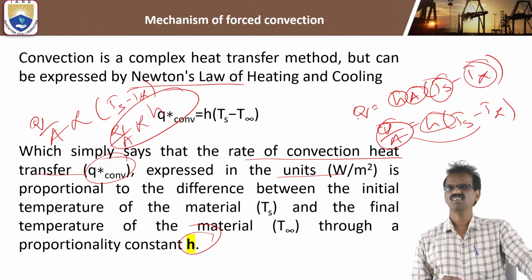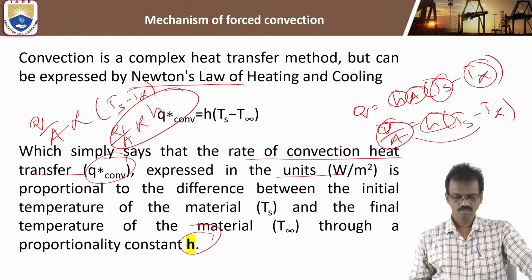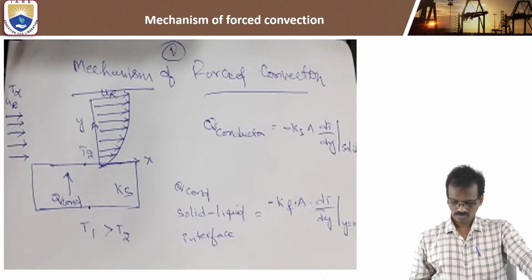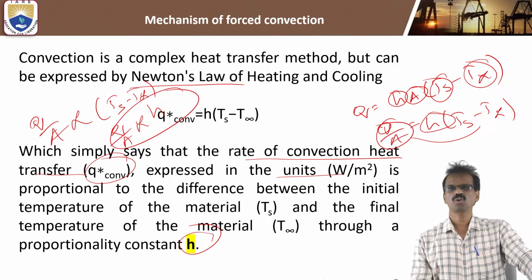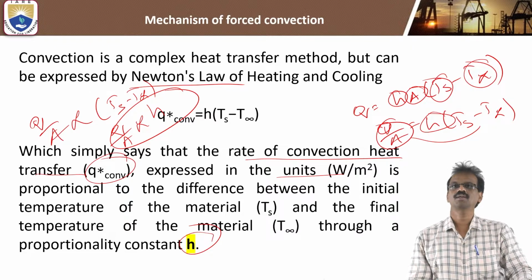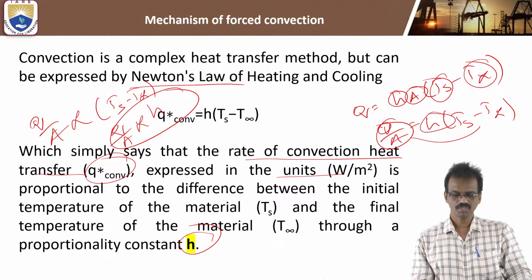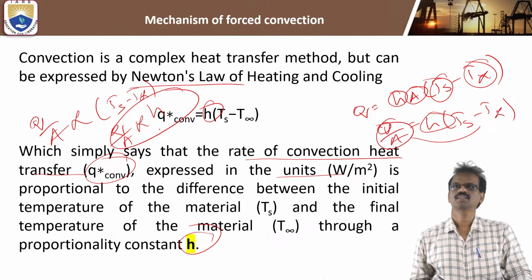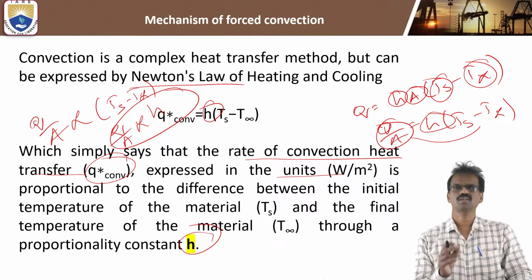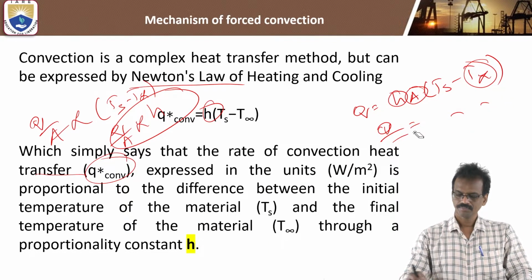But finding h for different fluids is very important, because fluid properties depend upon so many parameters, properties like density, viscosity, kinematic viscosity and Prandtl number. So by using those parameters, you have to find the heat transfer coefficient for the particular fluid. That is very important in this chapter.